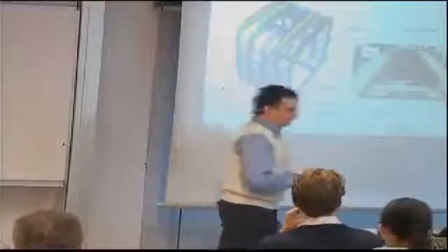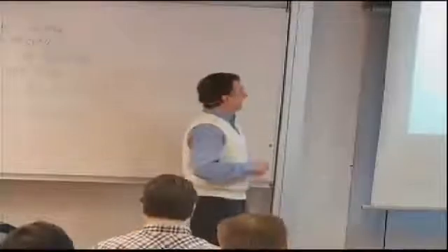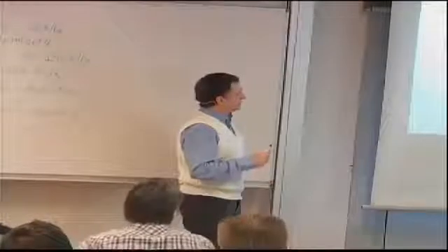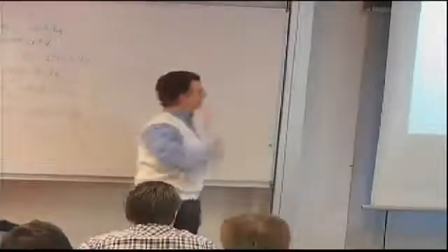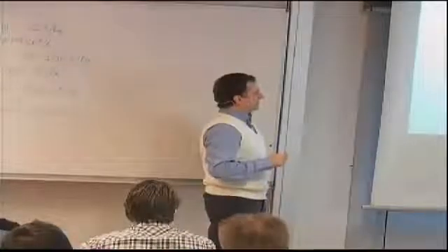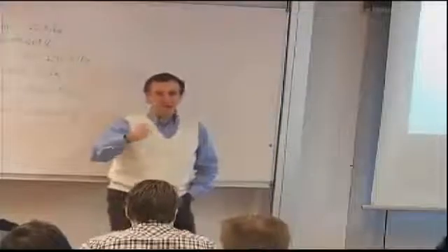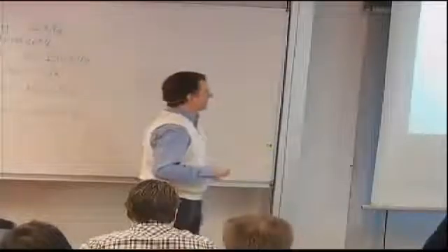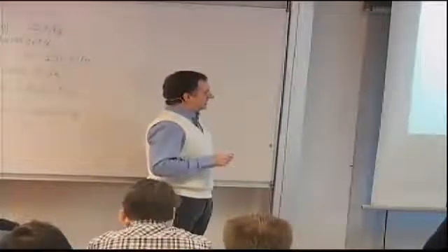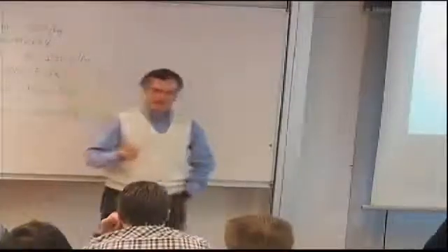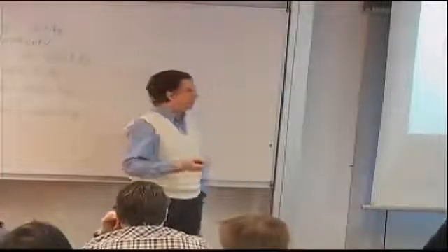So the structures consist of standard parts, and what I want to talk more about is going through some parts and talking about individual failure modes. If I have a standard skin, monolithic, which means that it's mostly a skin and it may have stringers or not, might be stiffened or not, then there's always the material strength as a possibility. Basically, you exceed the strength of the material, whatever that constituent is that might fail, fiber or matrix. But that is usually not even of interest, because you have to design the so-called damage-tolerant design. You have to design with typical damage present, because it's unavoidable that this will happen.